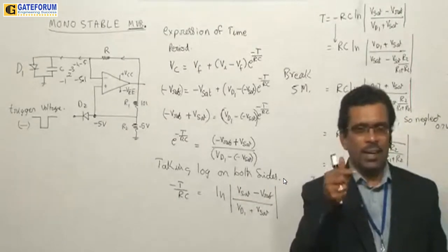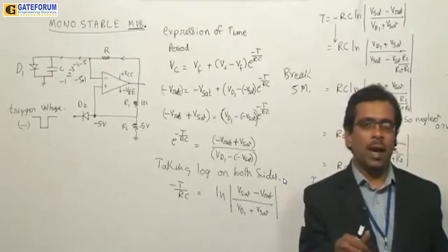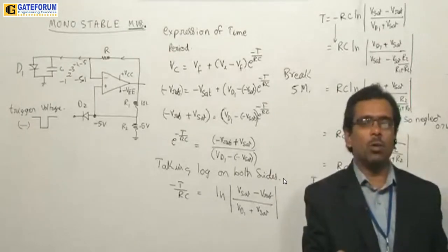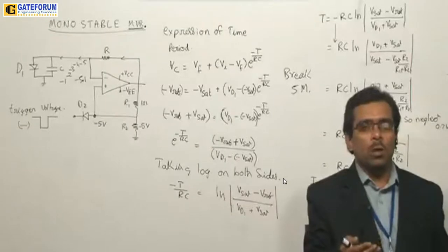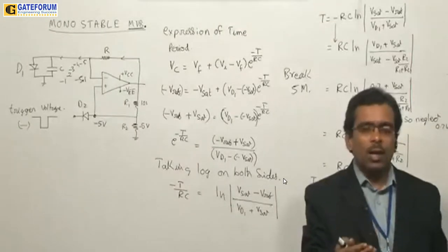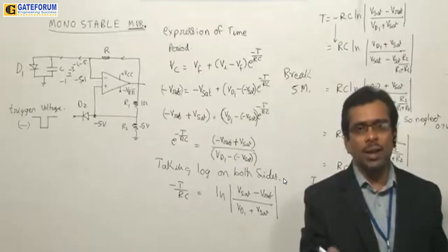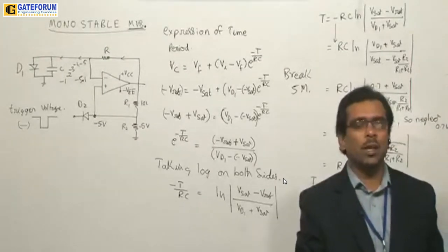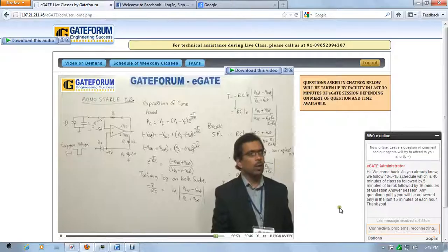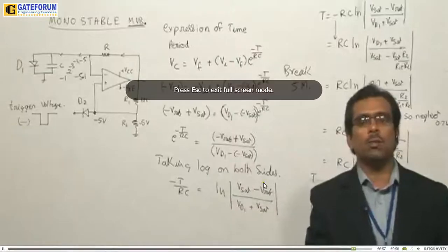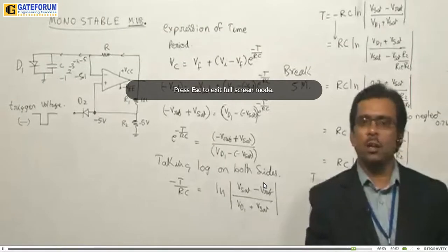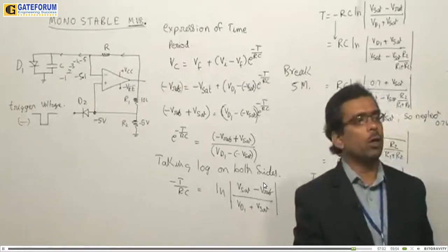If current is decreasing as voltage increases, and the output of that circuit becomes a periodic signal, then we consider that to be a negative resistance oscillator. SCR, and UJT in combination with the RC network across its shunt, will work. These two will work.